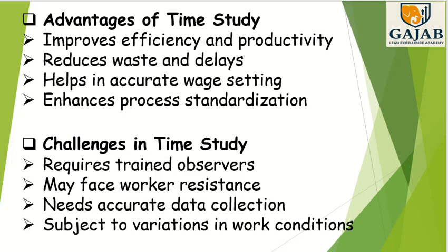And then challenges in the time study. Despite its advantages, time study has some challenges. It requires a very skilled analyst who has experience in the time study, and during the time study, workers may resist being observed because they fear they will get extra work. Additionally, accuracy depends on proper data collection, and work conditions must remain consistent for reliable results.